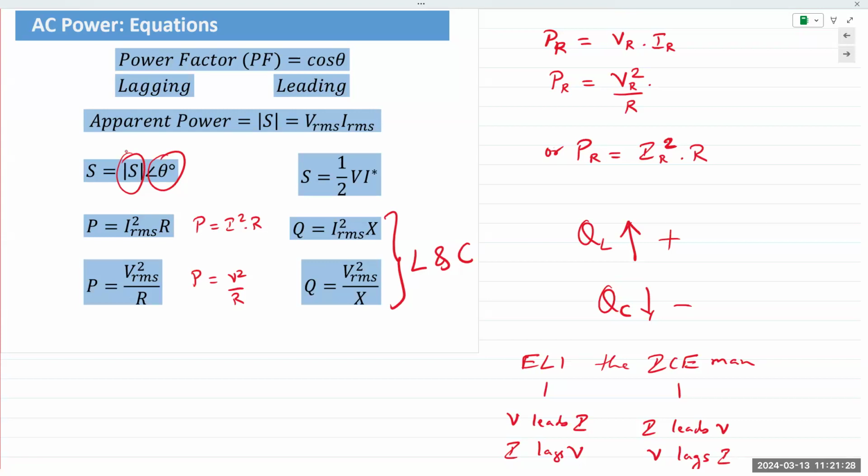We say reactive power is imaginary. We say reactance is imaginary. We say impedance is imaginary for an inductor and capacitor. But they have a physical basis in real life. The word imaginary is describing the mathematical representation of the reactance. Again, this is a common point of confusion for not just non-majors, even EE major students, when they first hear about this concept. Okay, when we say imaginary, it is the mathematical representation of the impedance.